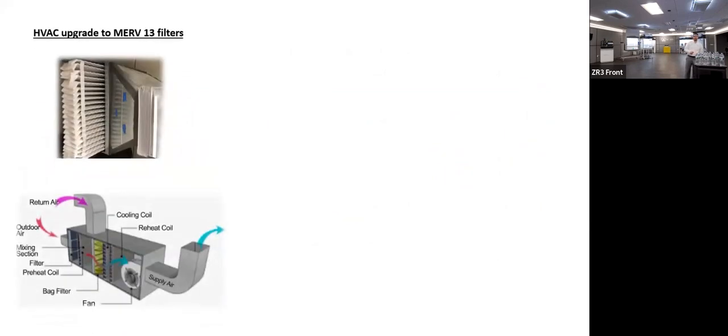And then, of course, we have the upgrade to the HVAC, to the MERV 13 filter, increase air changes, increase outside air. It is critical. You do want to have the highest grade filter you can have in your HVAC system, mainly because, yes, of the inside air, but also what's coming from the outside. Here we're on the East Coast, we're in Massachusetts. Last summer when we had the wildfires in the West Coast, our air quality index was, I forget, extremely high. And we do samples in our facility all the time. And we noticed a significant spike. So we wanted to get a baseline. Where is the spike coming from?